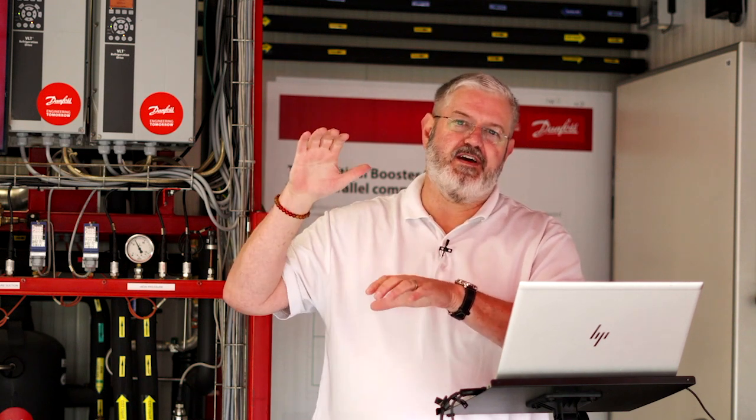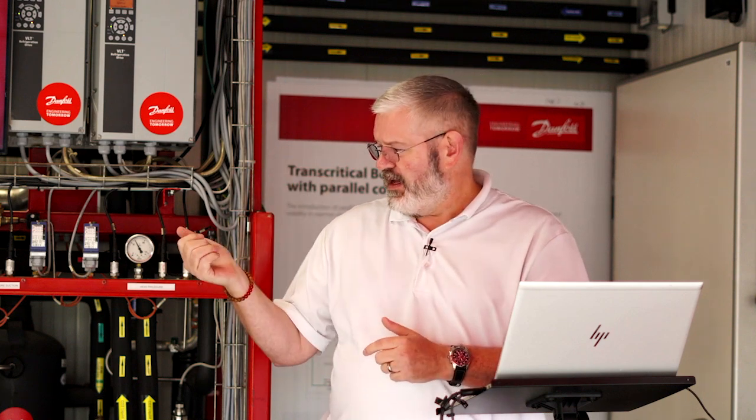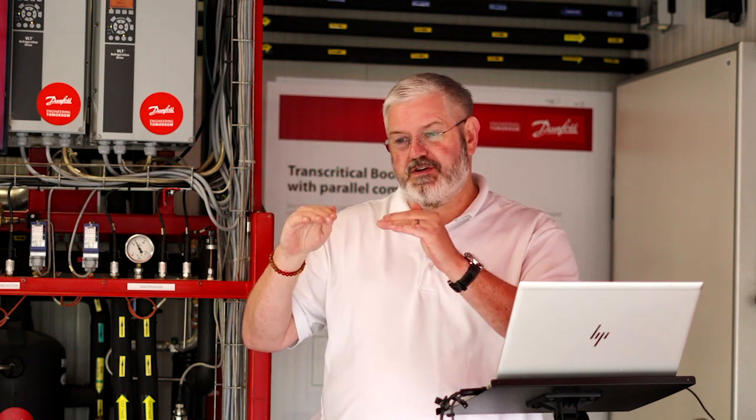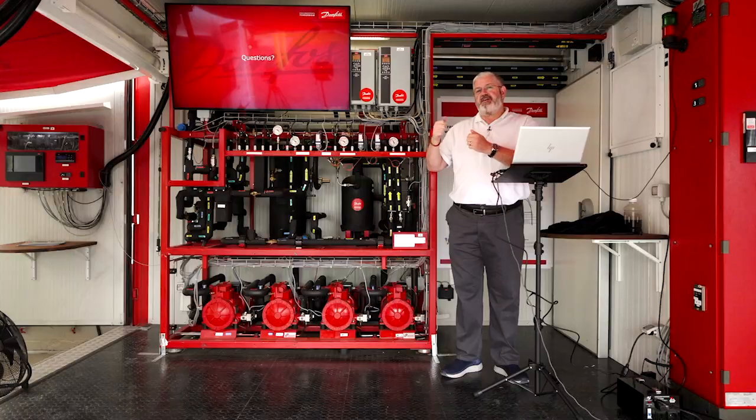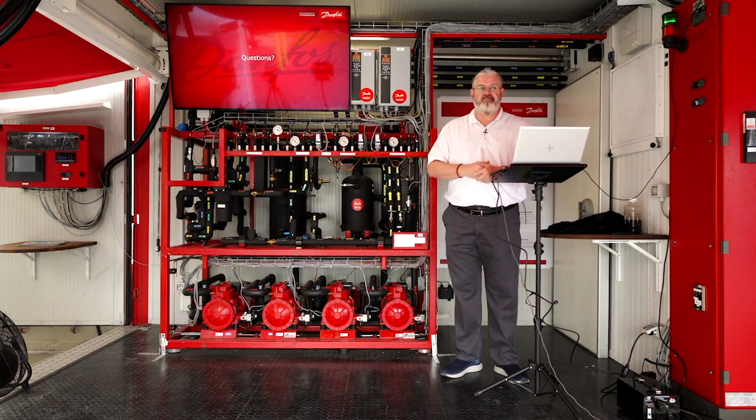You're going to have one or the other, but you can set it up to where you get below a certain ambient, you move to the high pressure, you get above that setting that kicked on the high pressure valve, you'll move back to ejector so you can start working on the Venturi effect and the lift for medium temp suction gas return. And then if you have both defined in the pack controller, it will by default use the high pressure valve as a safety backup should something happen to the ejector solenoids.